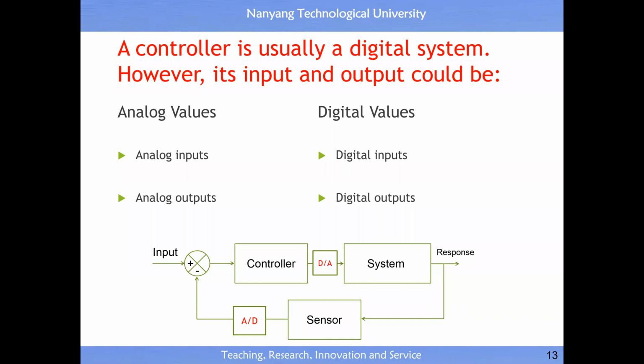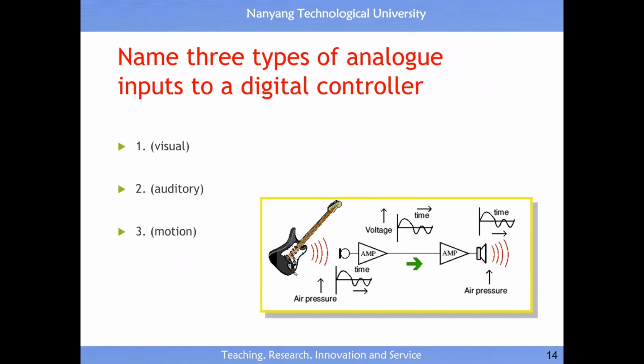So then in general, today, the machine's brain is based on the use of microprocessor, digital computer, or microcontroller. Microcontrollers are digital systems in nature, so a microcontroller can only output a digital number and can only take in a digital number, all right? This is why we need a DA converter and an AD converter to interface with analog systems and analog sensors. This is very, very important.